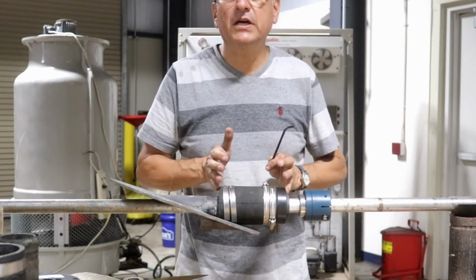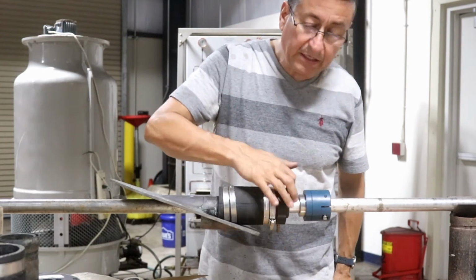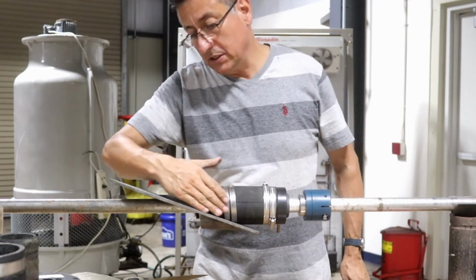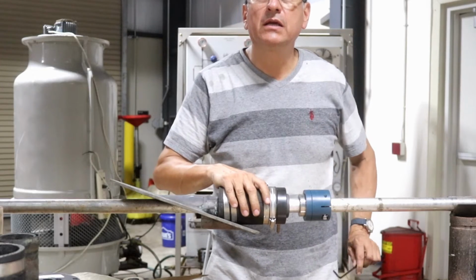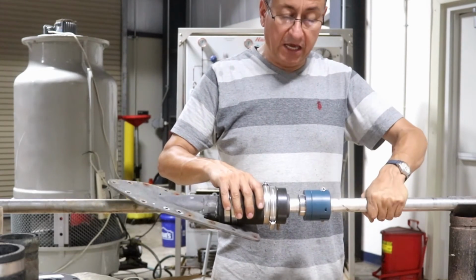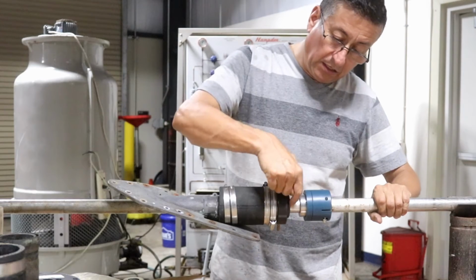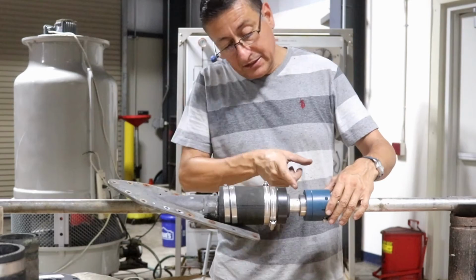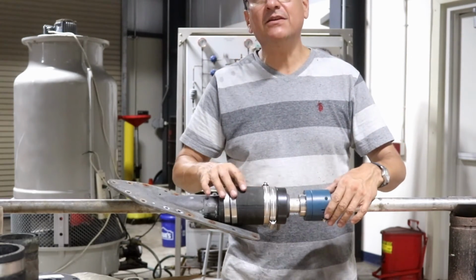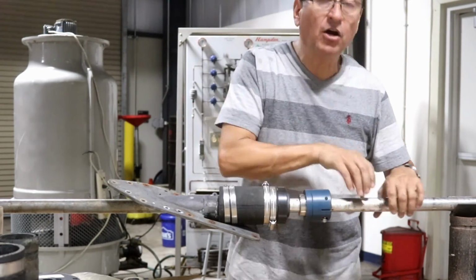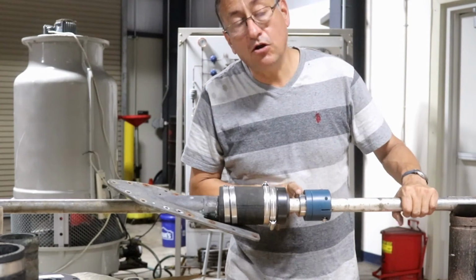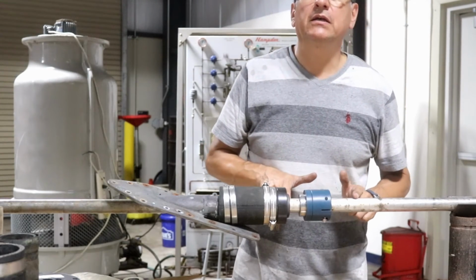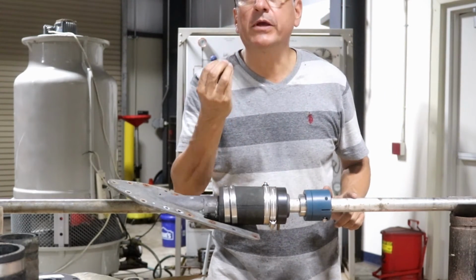Remember, this area, the stuffing box with the graphite, is fixed on the flange. On the flange, you bolted the hose clamps, and this is the flange. This is not moving. The shaft is moving free inside of the graphite. This is the collar of a graphite. And this is the stainless steel collar. The stainless steel collar will be bolted on the shaft. The stainless steel collar will be spinning at the same speed of the shaft in front of this graphite. The graphite works like a lubricant.